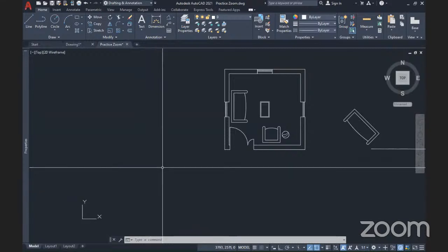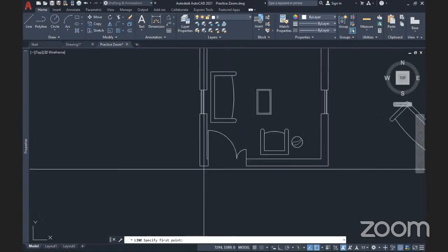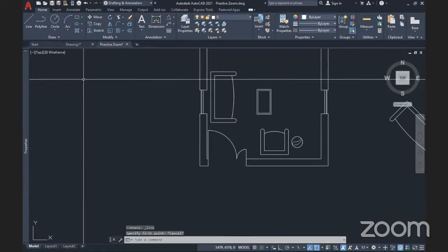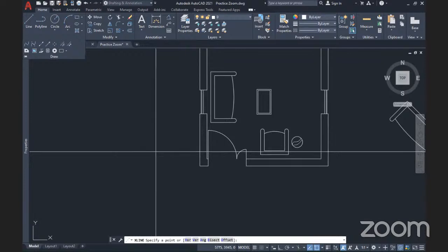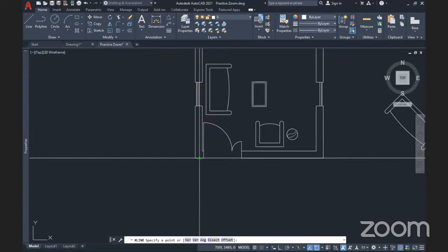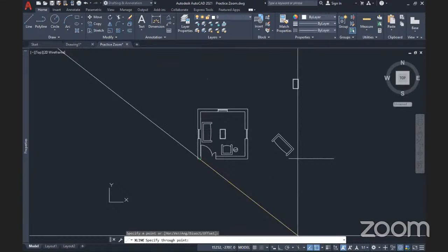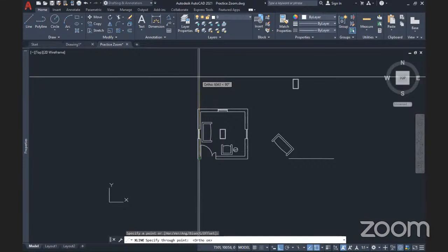Because the line is invisible, I am going to create my own mirror line for the class. But just bear in mind that this line will be invisible, but you can create your own mirror line. I will use a construction line. To create a construction line, just go to your drop-down menu and click on this construction line. Then pick your points. In this case, I'll pick the midpoint of this line because I want to use that as my mirror line, select it and then move upwards. I'll turn on orthogonal restriction to make it straight vertically.